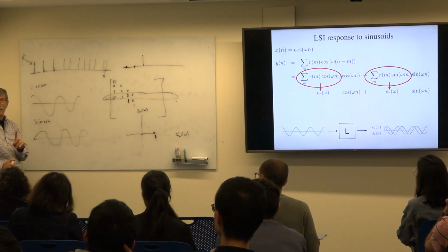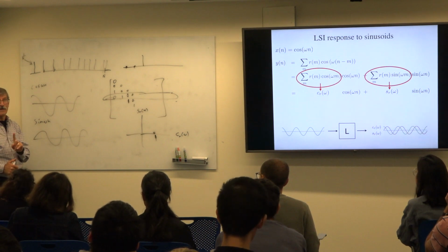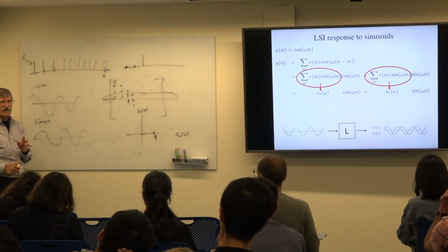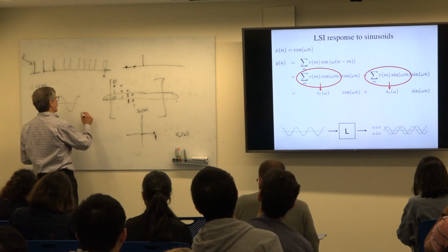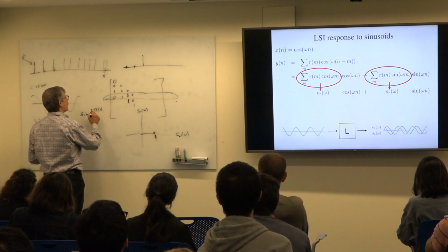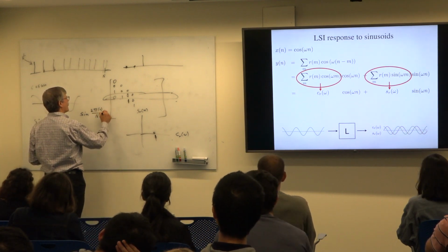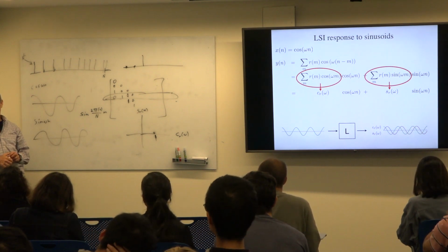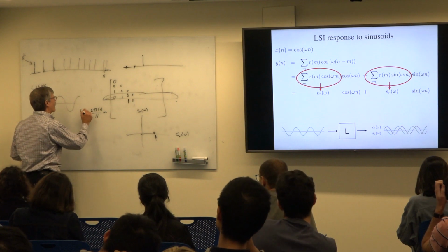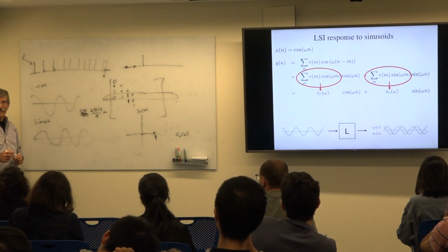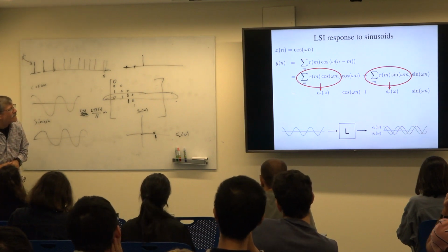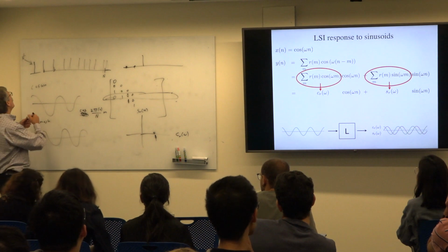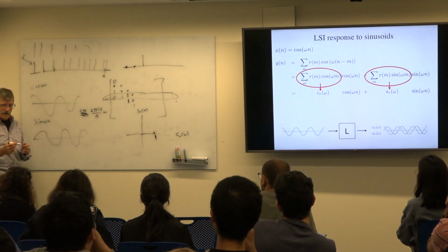Frequency 0. We've never talked about frequency 0, but k is allowed to be 0. Now frequency 0, as we'll see at the beginning of next time, is annoying and special because what's a sine wave at frequency 0? Sine of 2 pi times frequency 0 over capital N times time m. What's that wave? Zero. It's all zeros. You can't do anything with it, okay? So we're never going to actually use that one. What's the cosine equivalent of that? 1. It's all ones. It's our vector, okay? So there's only one CS omega, CR of omega that's not zero, and that's CR for frequency 0. And that's a dot product of all ones, 1, 1, 1, 1, 1, 1, 1, with this guy, and its value is 1.